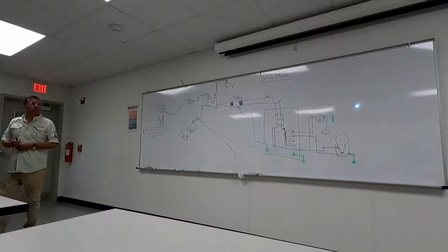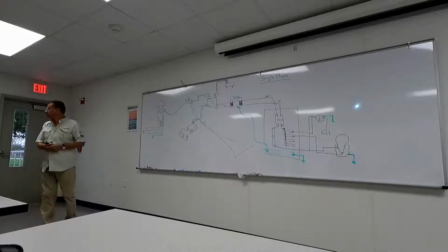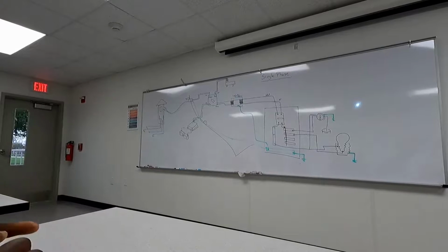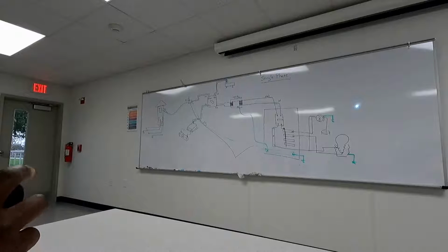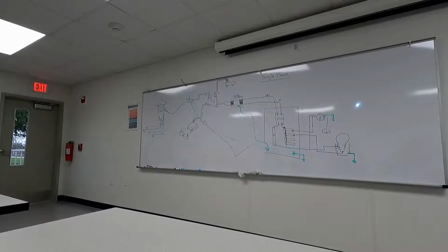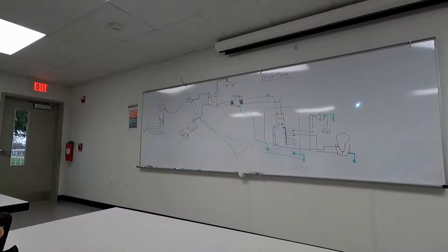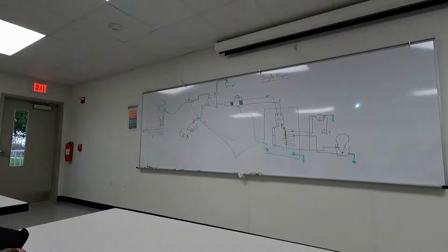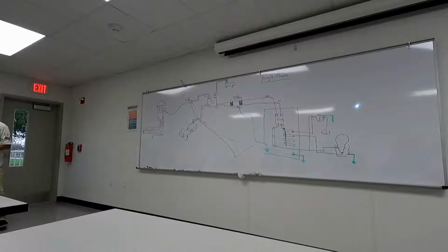No, it has a generator and everything. It doesn't have an isolation transformer. Do they have a galvanic isolator? It doesn't even have isolated. Not every boat has it. Yeah, I have. You have the galvanic isolator? You don't need that. A lot of our type of boats have the isolated transformer. On the boats that don't have the galvanic isolator, they have water heaters, like the Sea Ray. The water heater just rots right out. It just eats it right out.